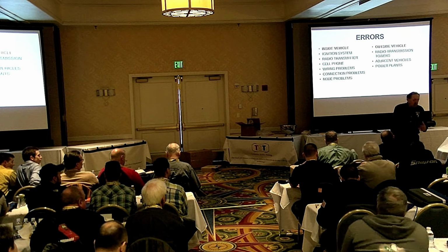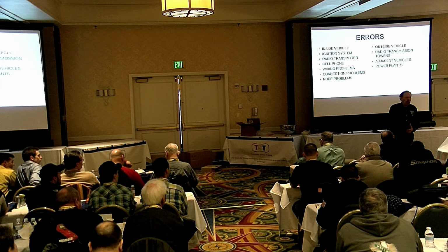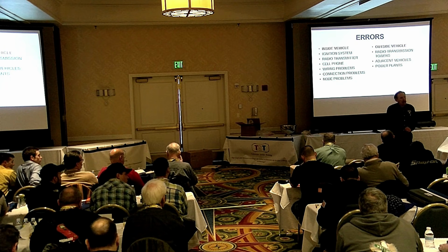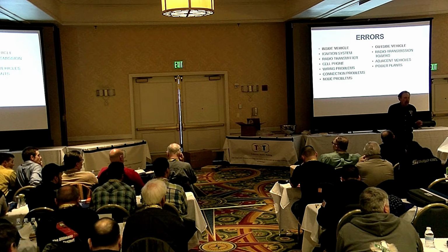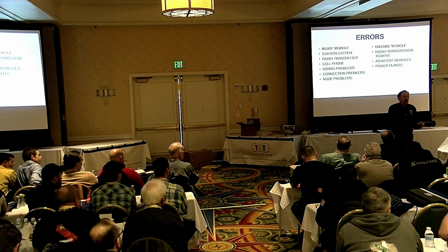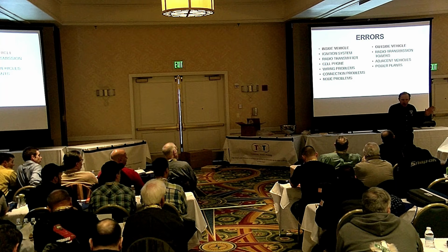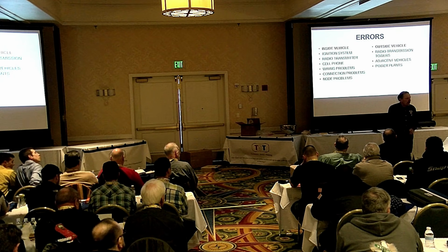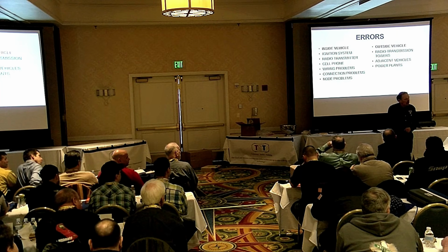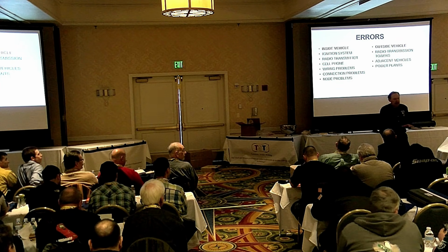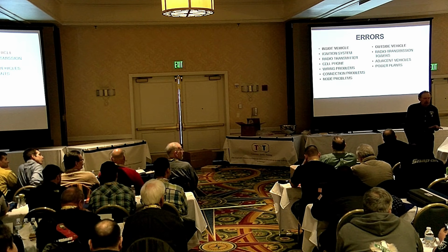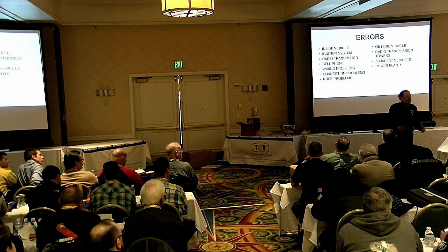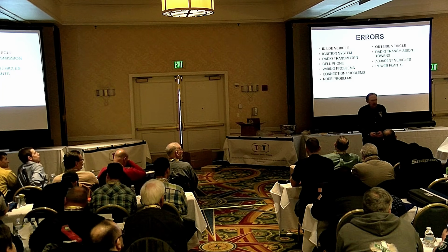FlexRay is a new standard. It really falls under something called X-by-wire. And there's a bunch of different systems. FlexRay is one of those systems under X-by-wire. That system has a clock that has a universal timing to it. But in pulse width modulated and variable pulse and all the stuff we covered, be very aware that these are event-driven buses like CAN is, right? Except the speeds are different because we have so many edge changes, right? So they're all very similar. So you can take a lot of what I'm telling you about CAN, and obviously it's not the same because there's different standards, but the arbitration fields, many of these things work out to be very similar, okay?